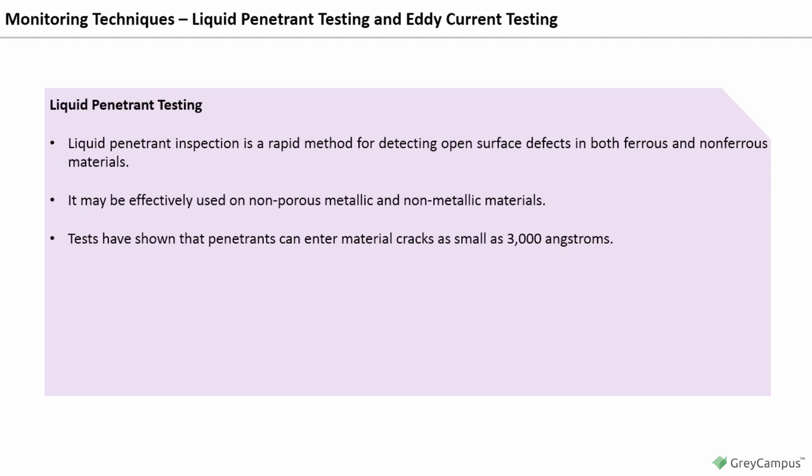The factors that contribute to the success of liquid penetrant inspection are the ability of a penetrant to carry a dye into a surface defect and the ability of a developer to contrast that defect by capillary attraction. False positive results may sometimes confuse an inspector. Irregular surfaces or insufficient penetrant removal may indicate non-existent flaws. Penetrants are not successful in locating internal defects.